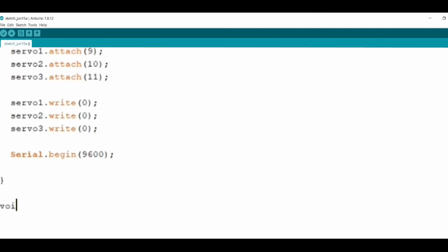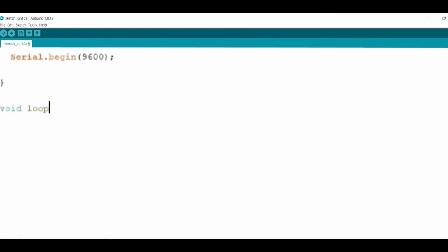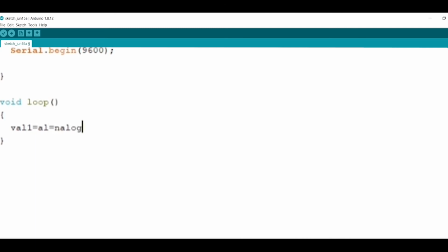After creating a setup function which initializes and sets the initial value, the loop function is created. Under void loop, the instructions which are supposed to be executed repeatedly are written. We know that when you bend the flex sensor which is attached to your finger, the change in resistance reduces the output of the voltage in the voltage divider circuit, and that reduced value is sent as the input to the Arduino. Moving on, the analogRead command reads the value from the specified analog pin and converts the input voltage range to a digital value.